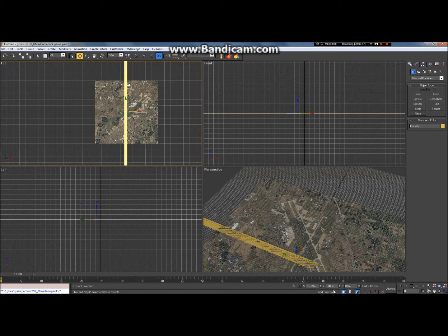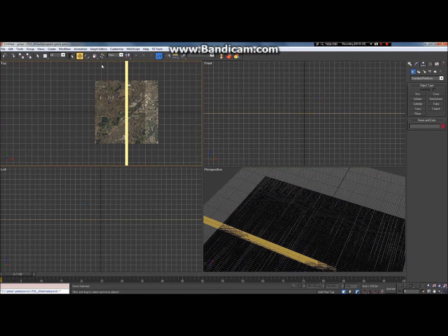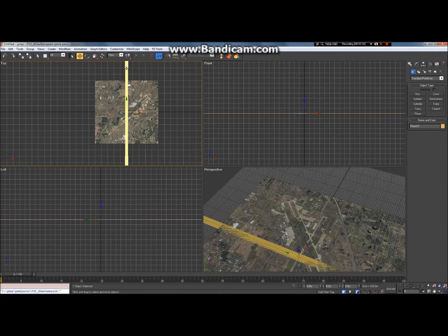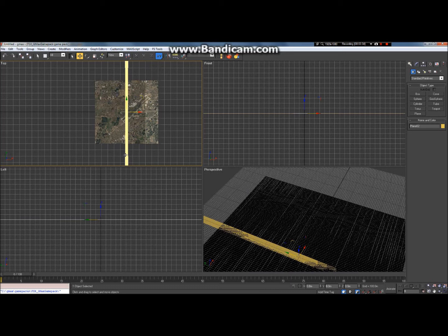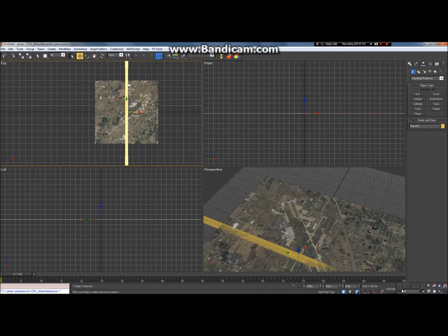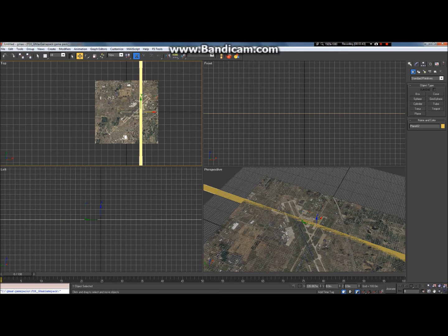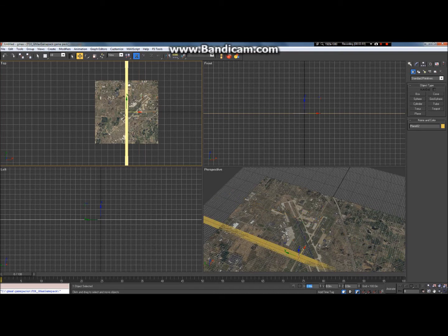Now let's make sure that we have the coordinates set to 0 on this. So we have the runway selected, and you can also select any object by just using the selecting box, or just click on the object and you can select it. Alright, so anyhow, we have the runway selected, and you just want to make sure that you center it. So let me just show you that again. So it's off center now. You can see down here that Y and Z are both at 0, but X is not. So just type in 0, press enter, and it's centered perfectly in our little world.